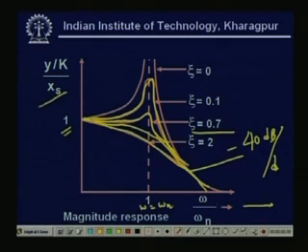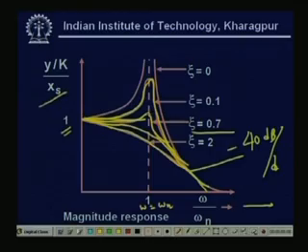So, I get an almost horizontal or flat frequency response. We are not supposed to use it after omega n, because at omega n, if xi is 0.1, there is a large overshoot. In many instruments this is not allowed, to avoid damaging the instrument. So, if I know omega n, I can limit the frequency response of my instrument. That is the reason we must discuss this point.